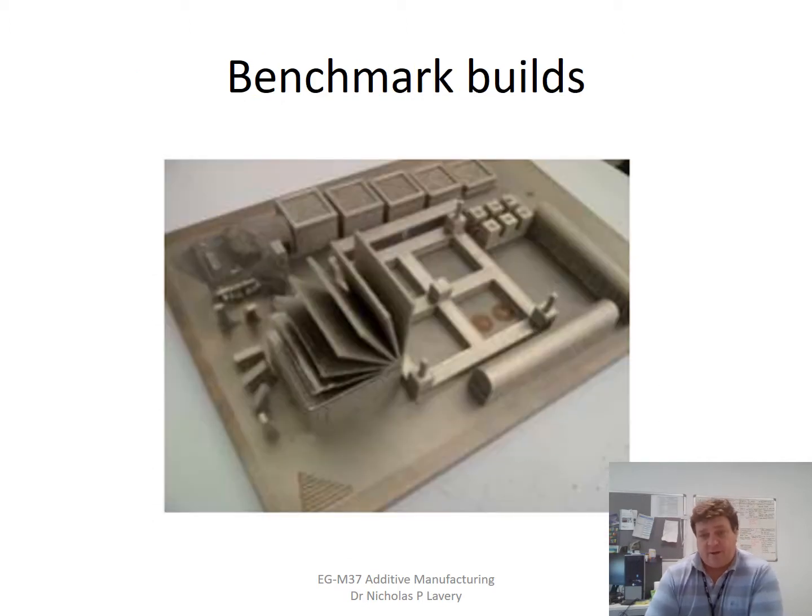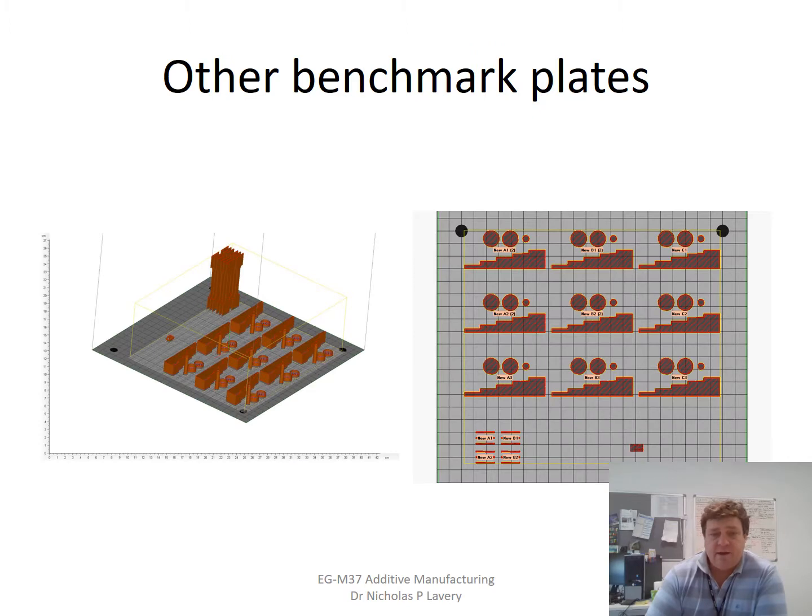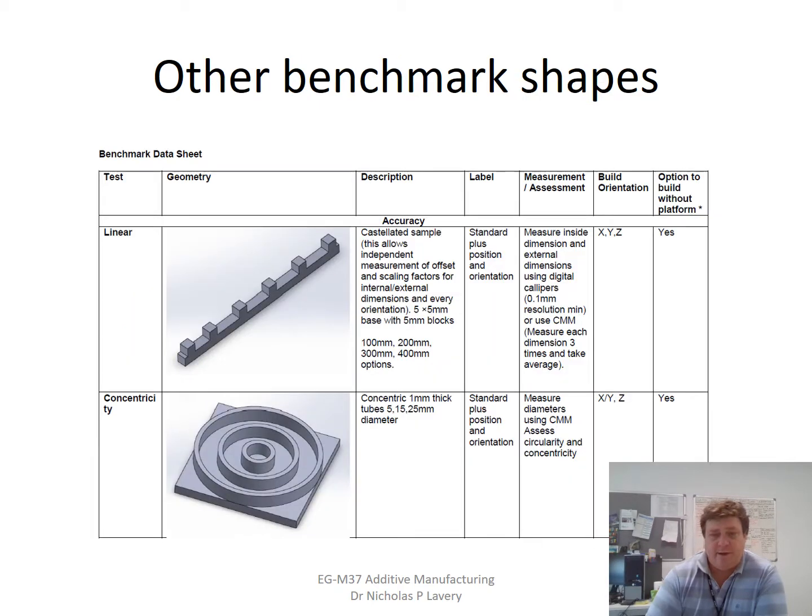Here's a rather poor quality image of some of the standard test pieces. So you can see horizontal test bars, you can see some angle test, probably to check the surface roughness and the build quality. You can see at the angles below 45 degrees that you've got various poor build qualities there. This is just another one. It shows some tensile test bars at the back and various small test pieces which are used, in this case, for thermophysical property measurement.